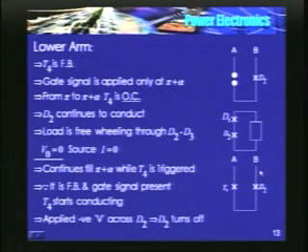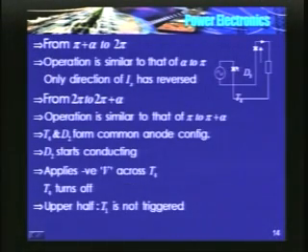In the negative half, potential of B is higher than potential of A, so a negative voltage appears across D2 and D2 turns off. So the equivalent circuit is now source, D3, load, T4 and back.